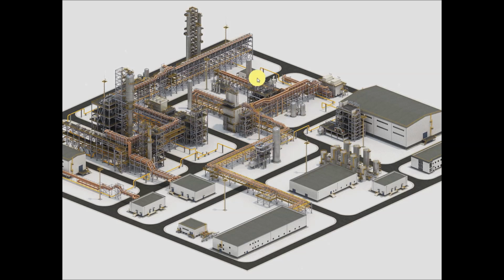So it'd be kind of risky to just send a schematic and let the supplier figure out the pipes, because you know that this is a restriction zone here. This is an alley for this tow truck to move through. So that's why I highly encourage you to render the tubes and the pipes when you create these projects.